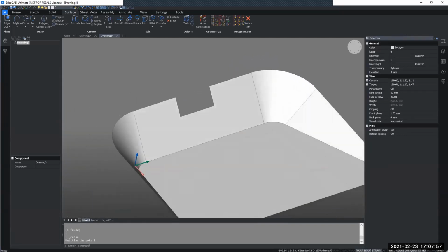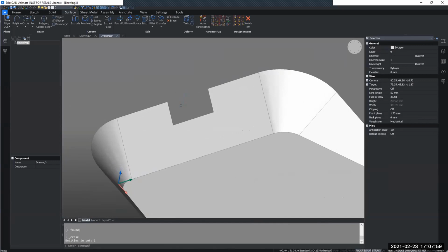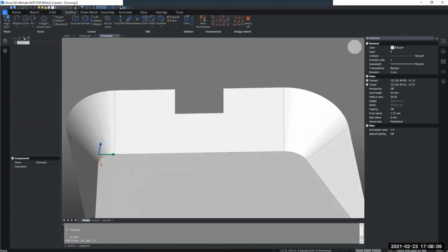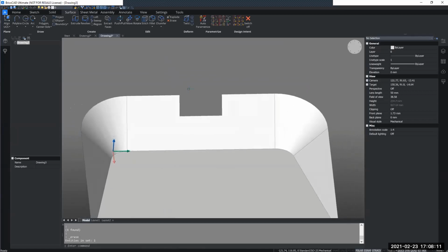And from here, we have room to make a handle. Now to extrude, we want to extrude the edges around here. I can select them manually again, or I can use the selection windows like I did before. If I use this window, it will select everything that touches it. So I can instead use the selection window by clicking and dragging to the right, so that it is covering all 3 of these edges.